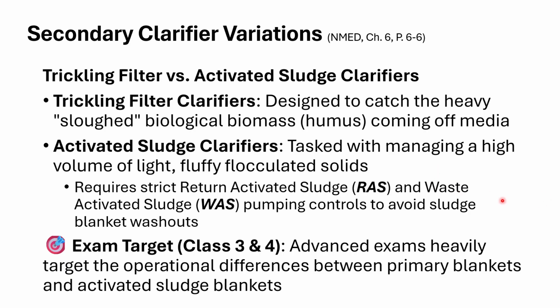So that's how we're controlling that sludge blanket at the bottom of the secondary clarifier. We're recycling the sludge with the microbes going to the inlet of the secondary clarifier, and then we're wasting the sludge to the digester and then off to solids treatment facilities, so that we don't have these mondo sludge blankets.